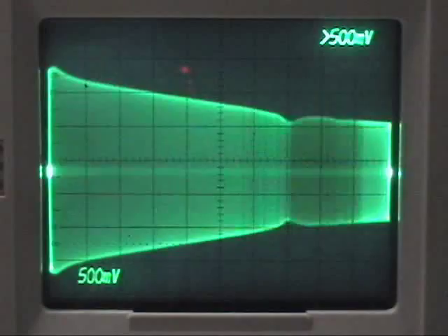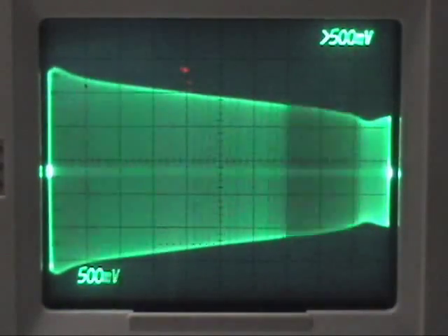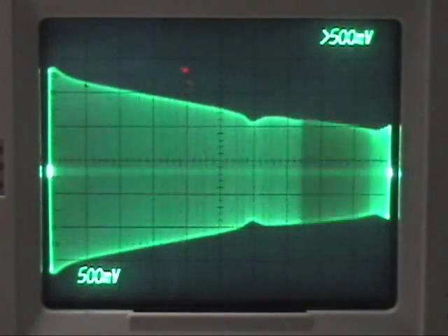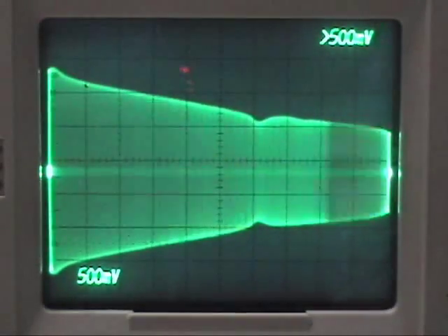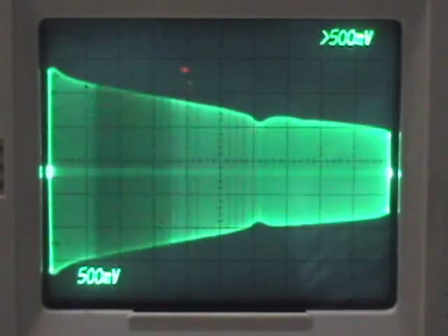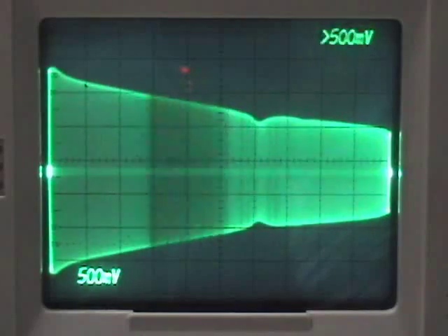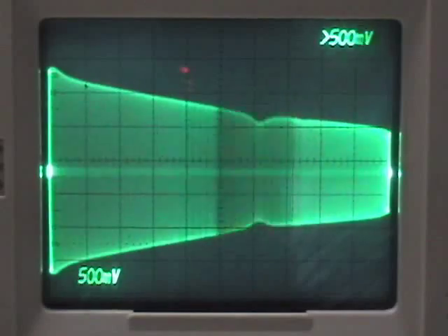We can come on down. There's 20 megahertz. Up here, there's 28. That's not bad. So we can go to 30, between 0 and 30, and be pretty good. Remember, we had 23 dB of gain, so if we lost 6 dB, we'd still end up with 17 dB of gain.